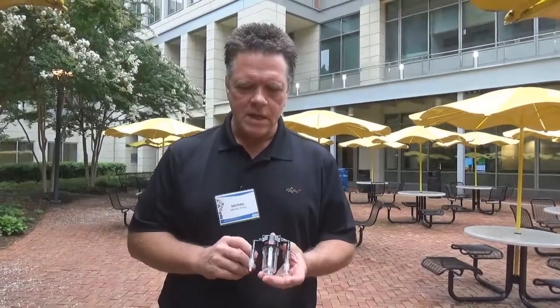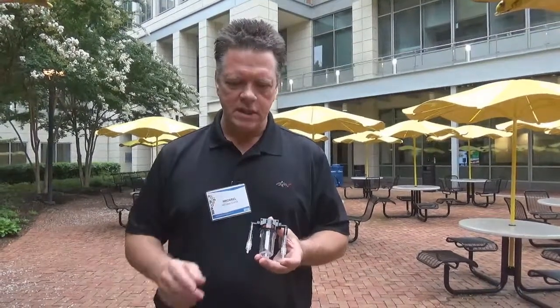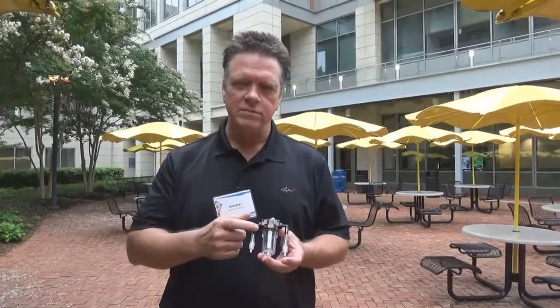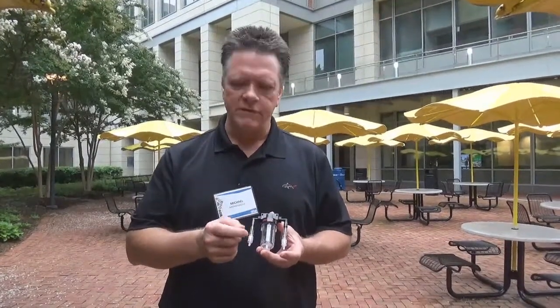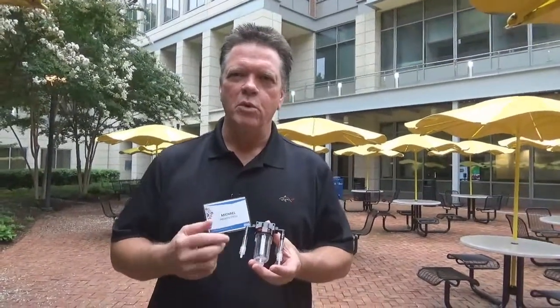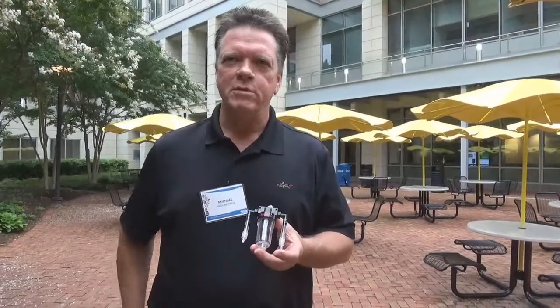until we came up with the final product. And was there anything in your prototyping that you learned that found its way into your patent application? Yeah, there was actually a couple things. One was where you put the flow restrictor in the device makes a lot of difference, in that if you were to put it in a down tube, you may get a siphoning effect, which means if you got some oil left in the tube, it's going to want to continue to flow down, and that's going to want to pull the rest of the oil out. There were a couple times where I'd wake up in the morning and go down, and there's a little pool of oil under my bike, and the reservoir was completely empty.